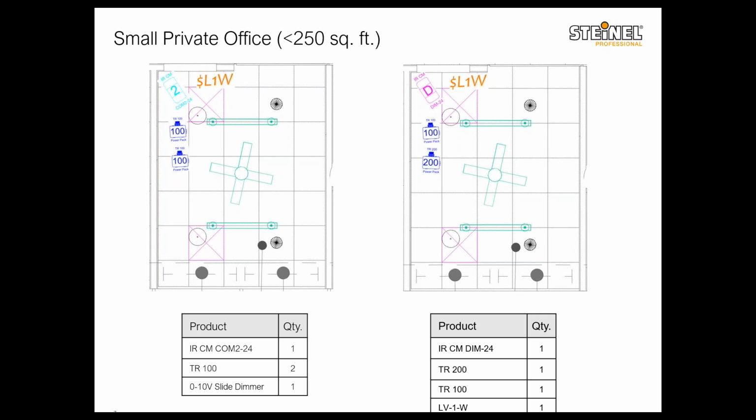The main difference, at least for this application, between a TR200 and a TR100 power pack is that our TR200 power packs have a built-in timer that helps us adjust the time settings on the power pack, and the sensor is just providing the occupancy signal to us. Or, in better words, occupancy and lack of occupancy, because it doesn't send anything when there is no occupancy.